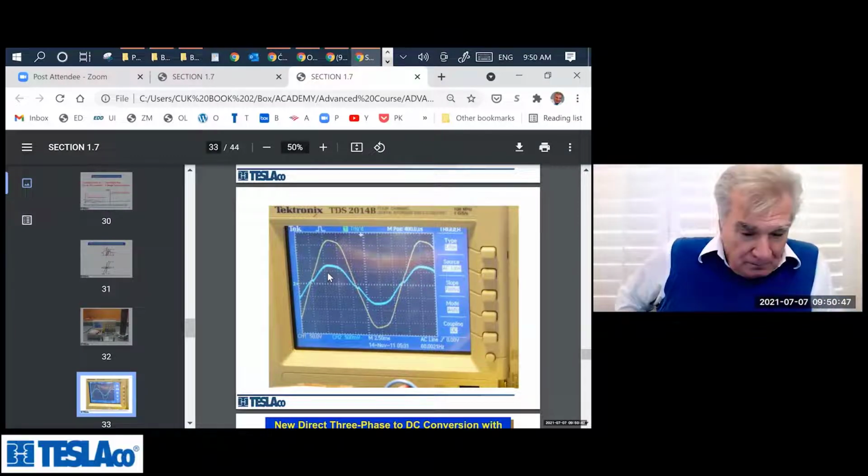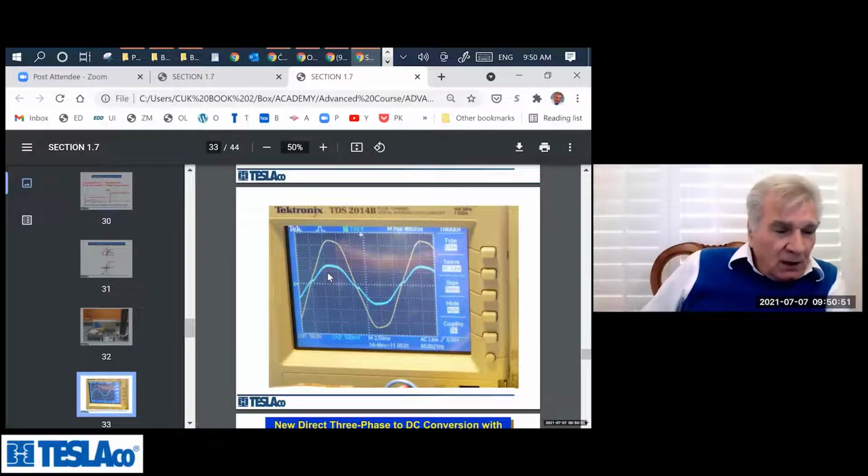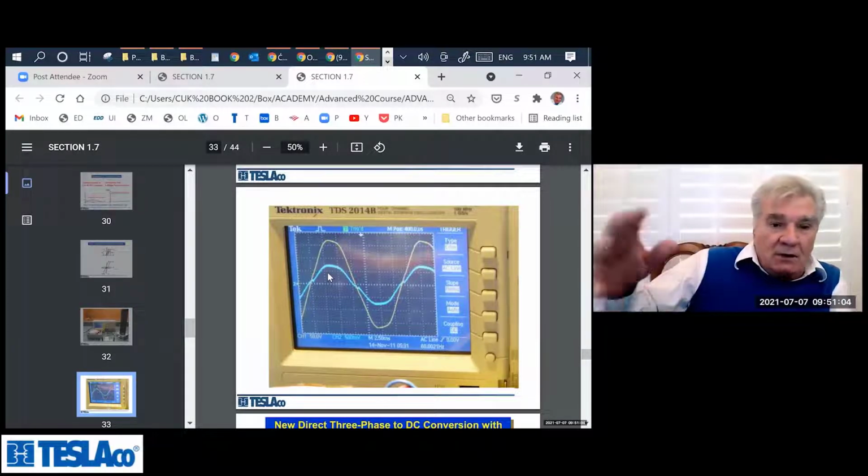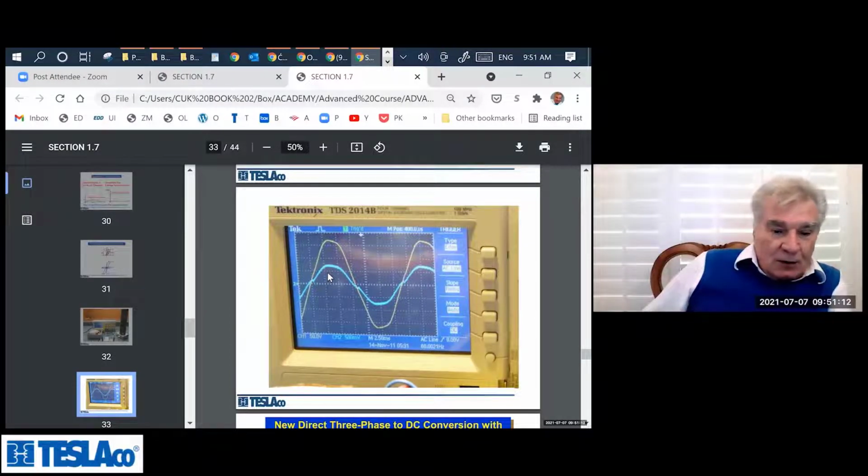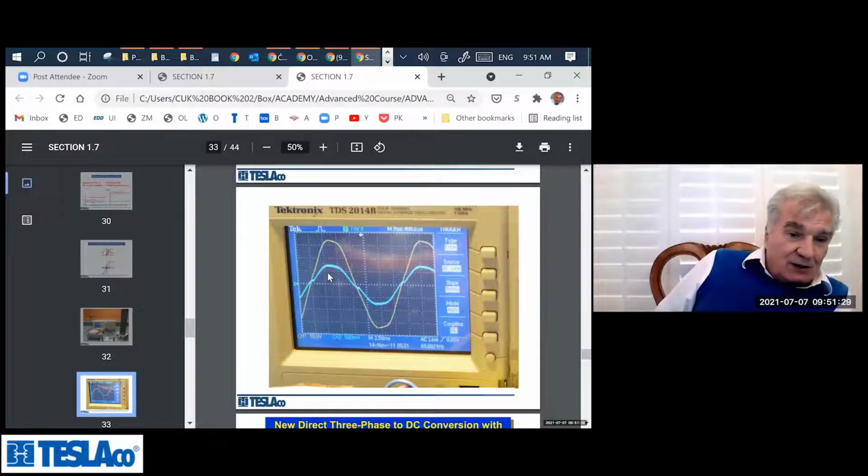And I don't know why utility companies don't require that, since it would be so cheap. You now have meters that give you the instantaneous time of what you spend on electricity and so on. But it would be very easy if they required that every household have a power factor correction circuit and draw the current in phase with the line, operating at unity power factor. Because the utility company is actually hurting. If you operate with a rectifier on a single phase, you have a power factor of 50%, half the power. They have to produce twice as much power to give the same active power, right? And you pay the same as with unity power factor.